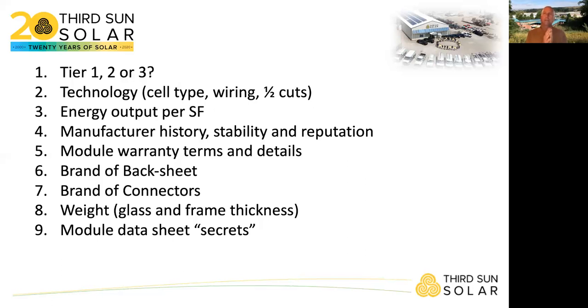This didn't used to be as big of an issue. But now that most of our rooftop systems are using SolarEdge optimizers or even Enphase brand microinverters, what we're finding is that some of the failures in the field in the industry come from incompatibility of the brand of connector. In fact, the National Electrical Code specifies that the connector must be compatible with the other apparatus that you're connecting it to. So that's one of the important things we look for.